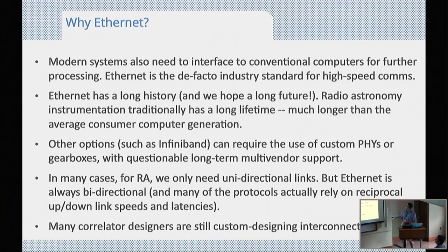I mentioned that we need to interface to other computers, and Ethernet's the de facto standard for that. Ethernet's also got a very long history, and we hope a long future, so it seems like a good match for radio astronomy. And then there's some other options like InfiniBand, which is often used in scientific environments and high-speed compute environments. The reason we steer clear of that is because you often need custom PHYs or gearboxes. So there's some custom hardware needed to interface with these things, unless you want to use the old standard, which then isn't really compatible or competitive. And there's some question about long-term multi-vendor support. Ethernet, many vendors make Ethernet parts.